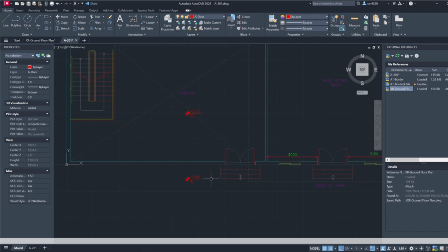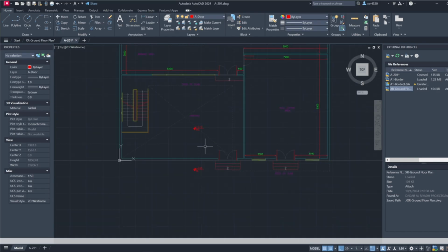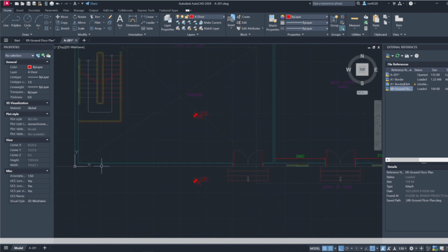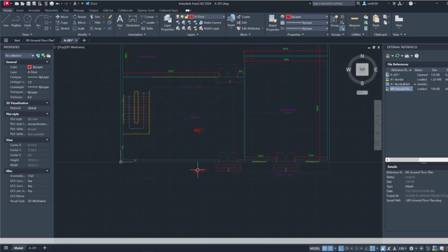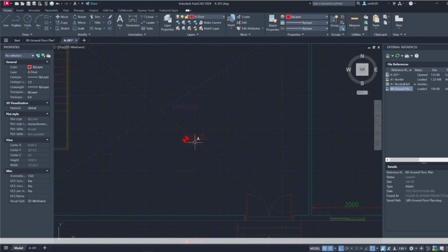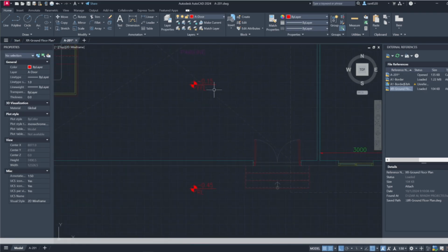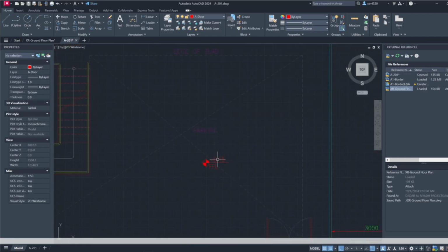In my future videos, I'll definitely show you how you calculate the slope, and how you have the slope for your cars to enter the house, if you have any sort of shutters over here. Anything of that sort. I haven't really created a shutter over here, but that's going to be a part of it too. So I'm having a 0.45 level over here, and I have labeled that as minus 0.45. And over here, it's not going to be as steep as this one, so it's going to be minus 0.15.